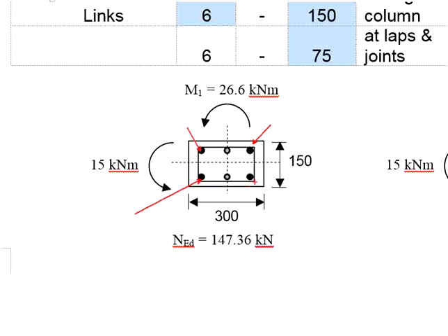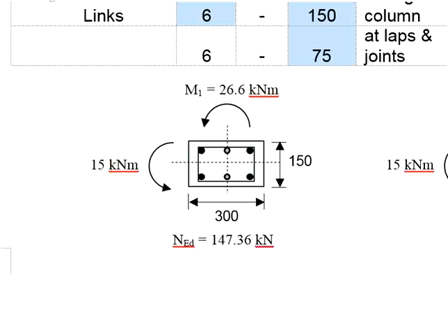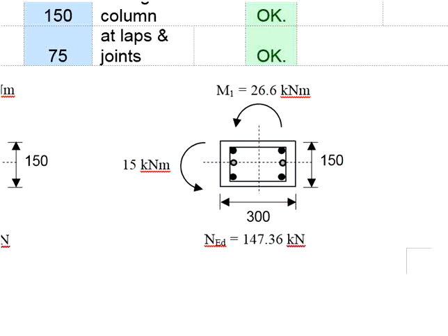4H16 plus 2H12. None of the reinforcement bar should fall at the center of the minor axis. You have to be careful about the arrangement of reinforcement. Make sure you don't provide reinforcement in this manner.